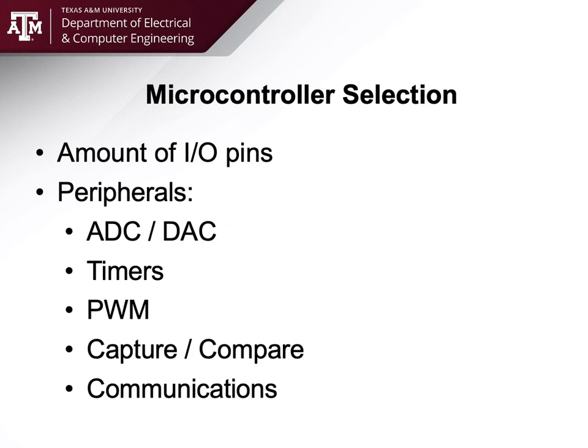If you have determined based upon your block diagram that you need 10 I/O lines, say 3 for a relay, 4 to talk to one chip over a SPI interface, so that's 7, and 3 more for analog inputs or something. Okay, great, that's wonderful. But if that's all the I/O your processor has for whatever reason, it only has 10 I/O lines, like a 14-pin microcontroller, basically.